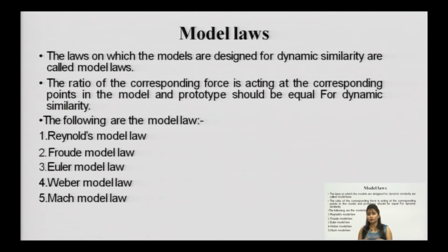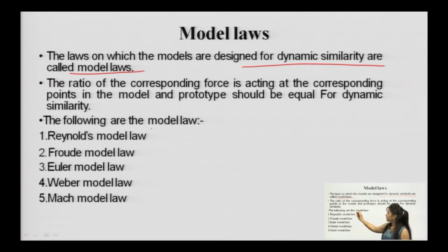The laws on which models are designed for dynamic similarity are termed model laws. Once again I will repeat, the models that are designed for dynamic similarity follow model laws, and hence the ratio of corresponding forces acting at corresponding points in the model as well as in the prototype should be equal. So, for dynamic similarity there is a condition, that it should follow the model law.